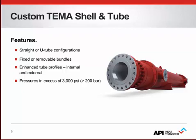Some of the features of the custom TEMA shell and tube can be generalized as shown. Straight or bent U-tube configurations can be utilized with either fixed or removable bundles as process conditions require. In general, shell and tubes are well suited for higher pressures, 3,000 psi or 200 bar and up, which makes them ideal for severe service applications.